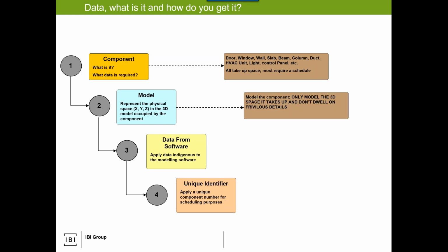So knowing what to model starts to get down to level of development. Are we modeling to contract documents? Is it conceptual design? What happens a lot is, are we pulling components from previous projects? Do we know what we're modeling? Have they been specified yet? Often in design, we model something that's really a geometric placeholder. So we model a window. We know length and width. We may specify 2 or 3 window vendors. So we may not know the particulars of the mullion, the width and the depth, but we usually have a maximum or a suggested.